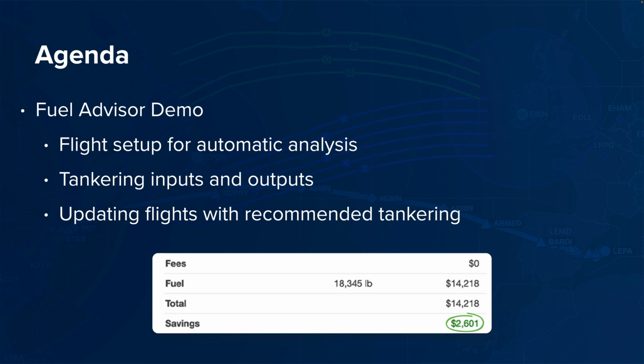Caitlin will then walk through the inputs and outputs of the tankering calculation itself, which of those are automatic and which ones are manually adjustable by you. And she will look at updating flights with the recommended tankering after the tankering calculation completes, and showing how you can update all of the flights involved at once with the new tankering information without going to each one to update the fuel manually.